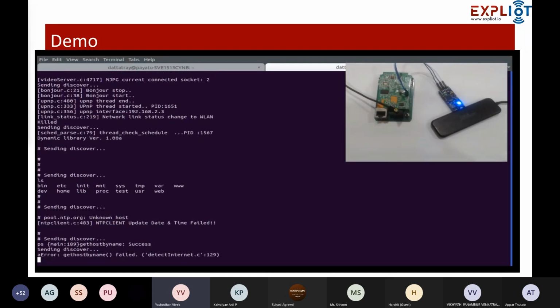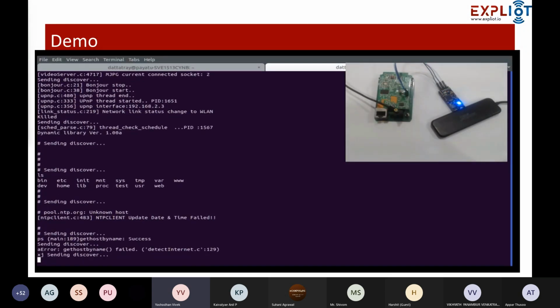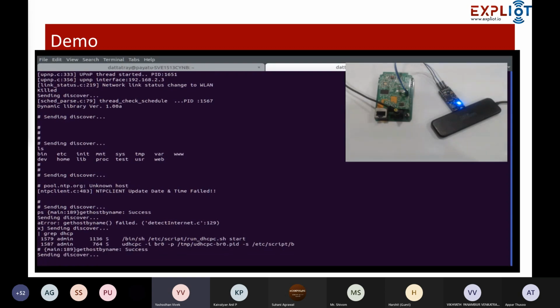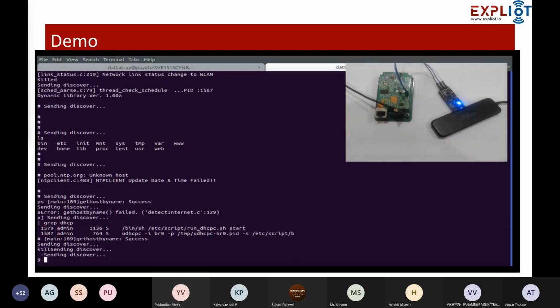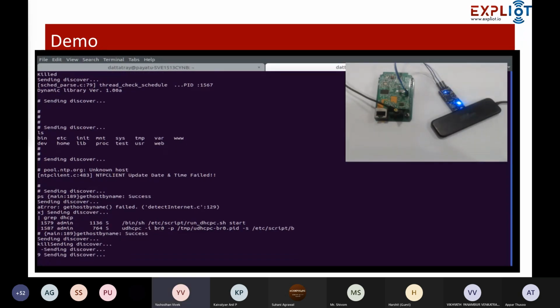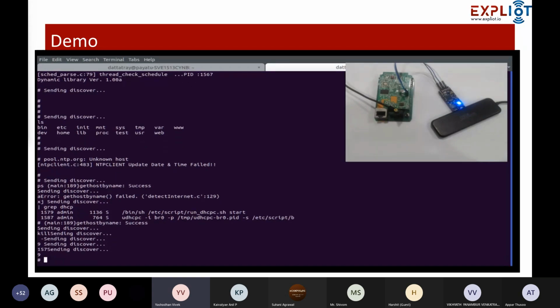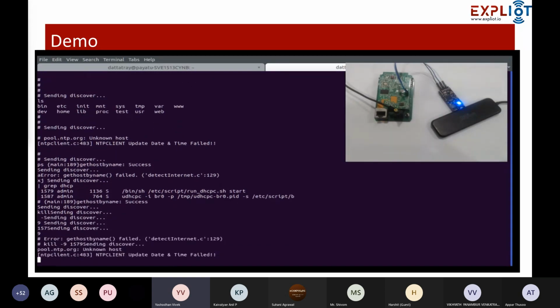So what we'll try to do is find some credentials with commands. What is happening is we're typing something, sending the commands. Since it's UART, it's two-way communication. Whenever we are sending something, we are also receiving. So that garbage you can see while typing something.